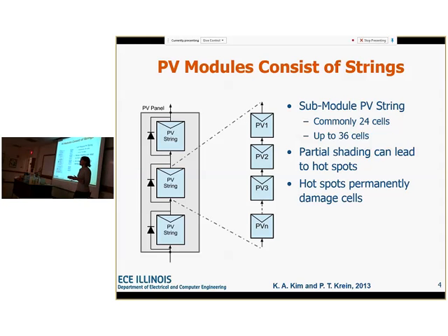Partial shading, which is also something we talk about a lot in the PV world, is one of the main culprits that eventually leads to hot spotting, and also reduces the amount of power you can get out of the cell, which is really the ultimate problem. Once you have a hotspot forming, it will damage the cells.